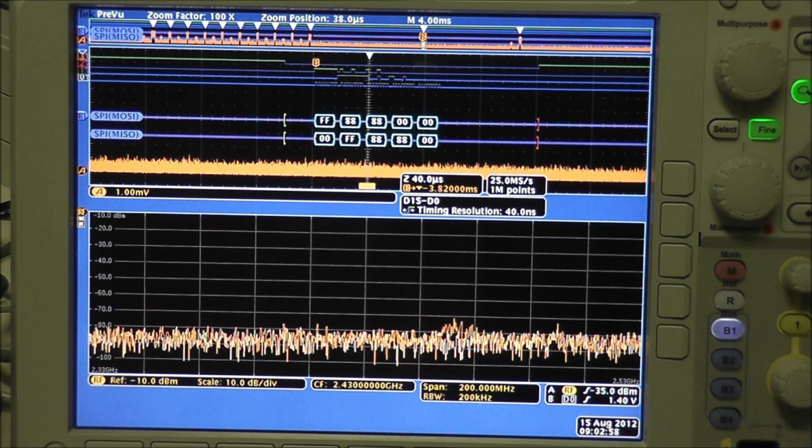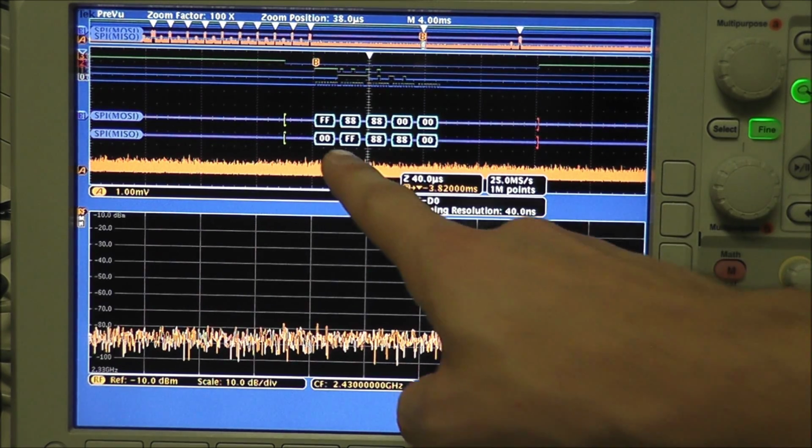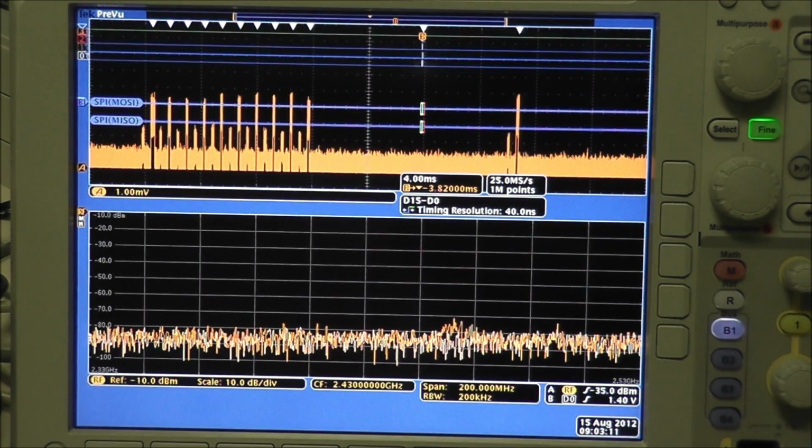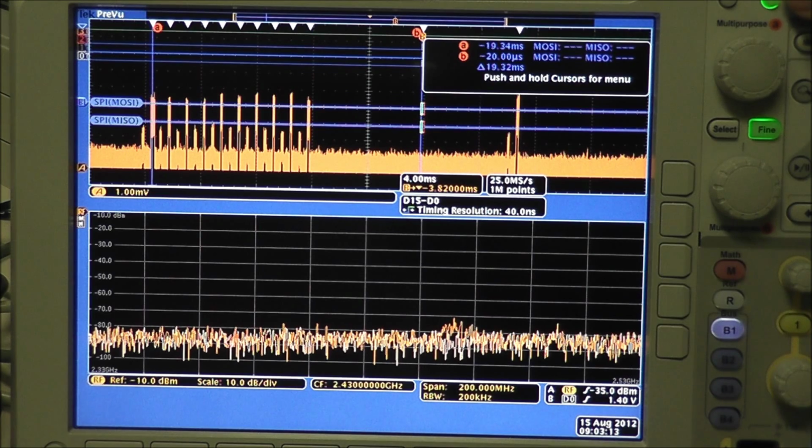the microcontroller through SPI. So this next part here, if I pan over, you can see the SPI here, and so you can see that I have a MOSI and a MISO, and so I've successfully transmitted my data to the microcontroller and back from the time of leaving the Bluetooth from the Wii controller.